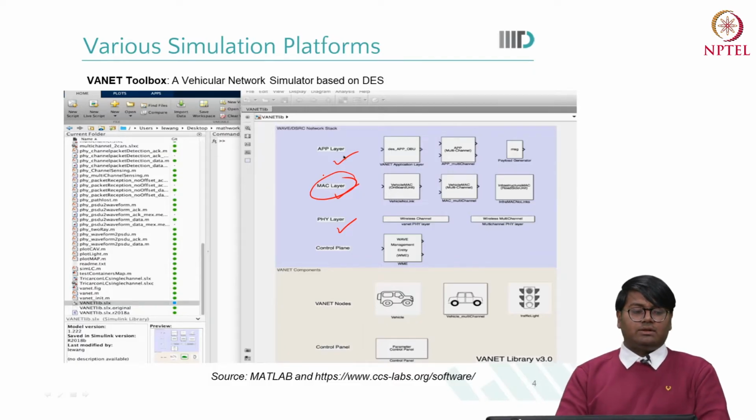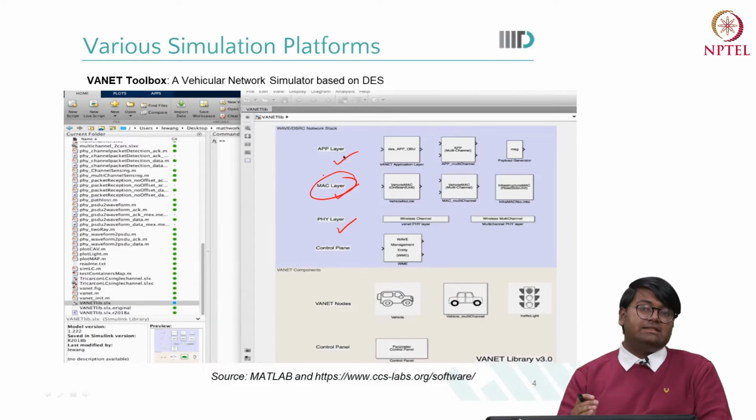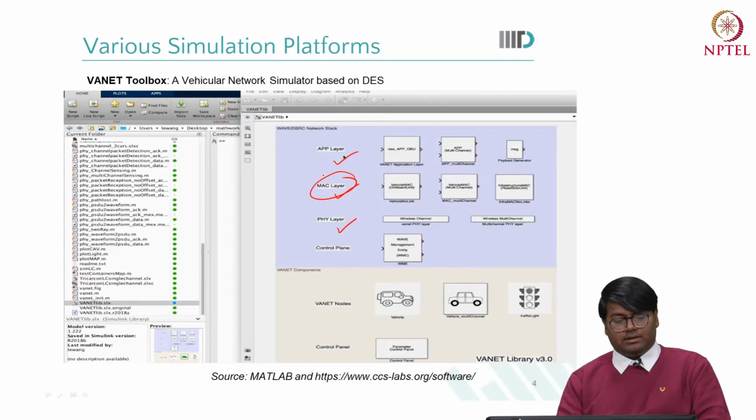In the application layer, the vehicular mobility models and message creations are handled. Messages like lane changing messages and basic safety messages are generated in the application layer. This application layer also incorporates various vehicular mobility models, such as the lane changing model and the car following model. These are the two mobility models that enable users to simulate the lane changing and braking actions.